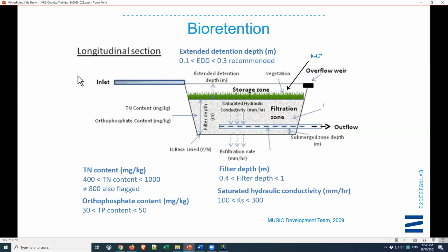Certainly, some guidelines say 300, some 400 mil is a minimum. What we have seen in the field is that systems that are 300 or 400 mil deep are at high risk of just drying out really quickly and the plants dying. You can add to that Dean's comment or question about the wetlands before that: if you get a fairly dry period through summer and not a lot of rain, things can dry out pretty quickly. That's doubly the case for your bioretention or rain gardens. So you do want them a bit deeper, where you can manage it.